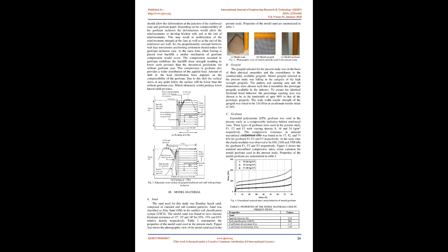Figure 1 shows the schematic cross-section of the geogrid reinforced soil wall with a 0.23 H wide footing: (a) footing at 0.5 Lr (length of reinforcement) from the crest of the wall; (b) footing at 1.78 Lr from the crest of the wall. Strip load applied at the top of the reinforced zone should induce the maximum strains in the top layer of reinforcement, which would reduce further for the following reinforcements towards the foundation layer.